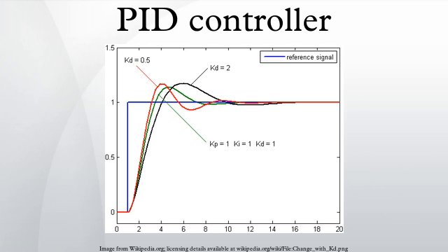For example, in most motion control systems, in order to accelerate a mechanical load under control, more force is required from the actuator. If a velocity loop PID controller is being used to control the speed of the load and command the force being applied by the actuator, then it is beneficial to take the desired instantaneous acceleration, scale that value appropriately and add it to the output of the PID velocity loop controller. This means that whenever the load is being accelerated or decelerated, a proportional amount of force is commanded from the actuator regardless of the feedback value.